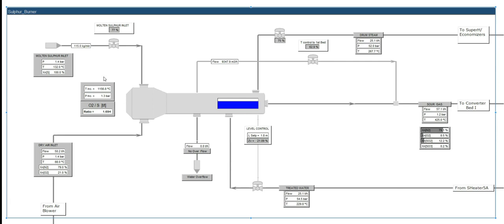The expected reaction is that our temperature in the incinerator goes up. We should see the higher production rate of the steam. Our control valve should close the hot gas bypass to maintain the temperature at 425, which will increase once we increase the sulfur flow. Also, the oxygen going to the stack should decrease as it's going to be consumed in the incinerator for the production of the SO2.